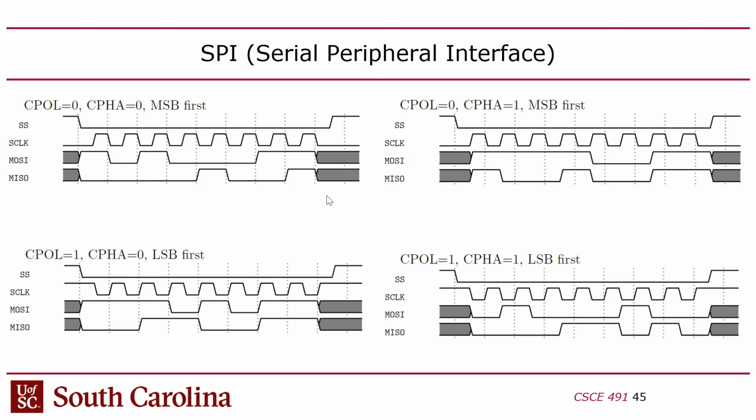Now you might say, well, I mean, it's kind of impossible for that, right? Because a CPU can really only execute like 1 instruction per clock. How could you have enough instructions per clock to track these transitions through? Well, no, because keep in mind the CPU's clock is going to be faster than the SPI clock. There's 2 clocks we're talking about now, right? The CPU clock on an Atmel chip is 16 megahertz, whereas this is going to run at a megahertz at best. So the CPU is going to be able to execute like maybe 16 instructions for every clock cycle on this bus. So in theory, you could bit bang this.